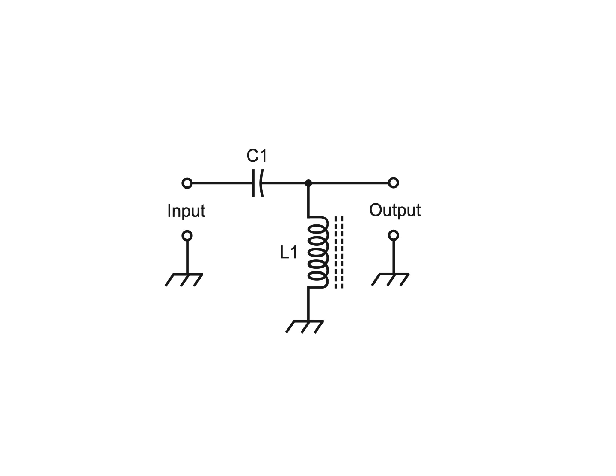In this case, we have a so-called high-pass filter because it lets signals go through more easily as the frequency increases. The exact frequency at which the transition from high attenuation, or lots of signal loss, starts to change over to low attenuation, little or no signal loss, depends on the values of the capacitor and inductor.